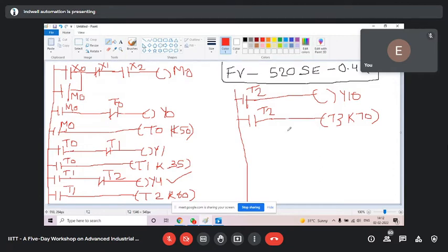So when forward direction is on, at the same time let us make green on, because once T1 comes, see this, once T1 gets on, it is continue on, correct? T1 is continue on because timer is set. So once T1 comes, let us make Y2 on, that is your green color lamp. Got this? So this you can use T1 and Y2.